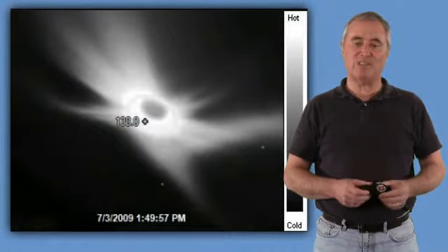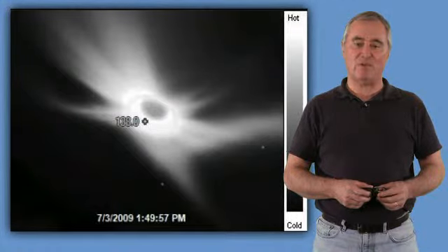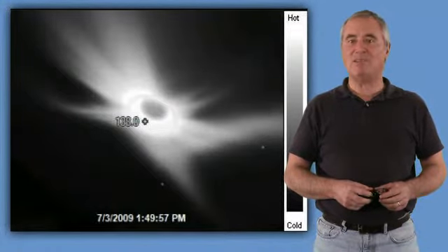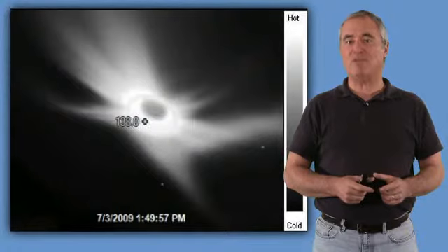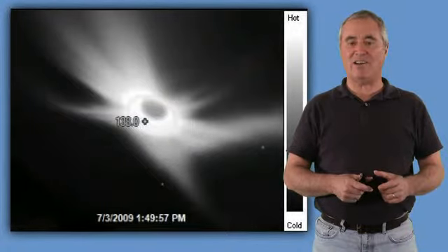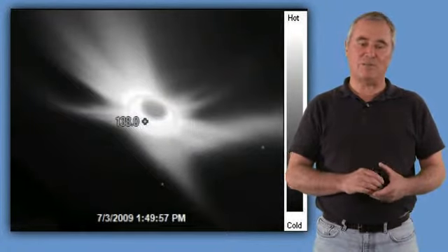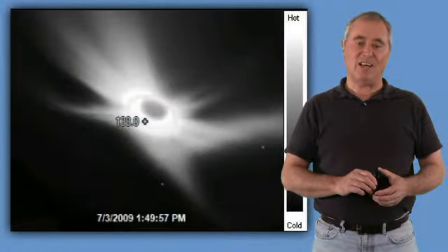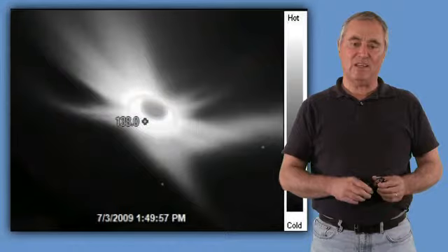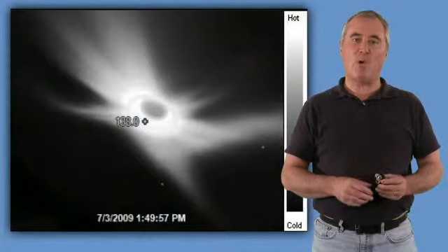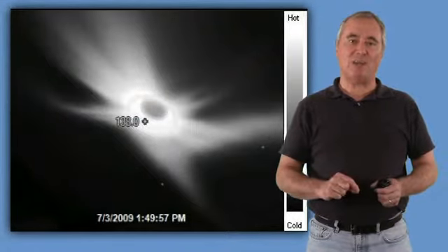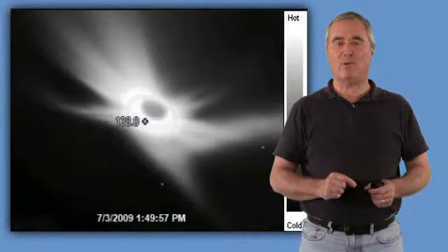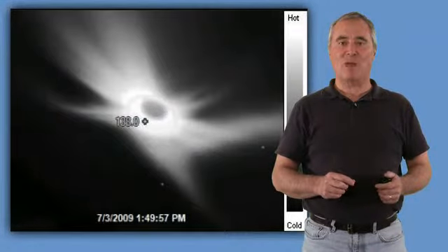And here's a summer air infiltration leak. It's around a simple recessed light fixture where hot air leaks out of the attic and into the fixture. And we see the hot streaks across the ceiling level. This illustrates why it's so important to depressurize the house as we film it in infrared when we look for these leaks.